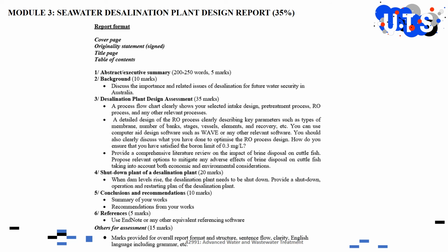Second, you can make a detailed design of the process that clearly shows key parameters such as types of membrane, number of banks, stages, pressure vessels, elements, and recovery, etc.